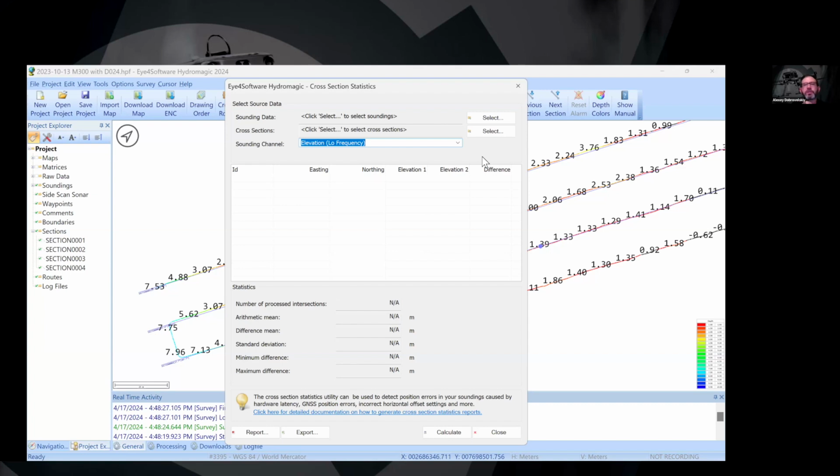And actually, if we do bathymetric surveys in some rivers and lakes, the elevation of the water surface can be different at different times because of tides, because of actually the variable amount of water in a pond, for example. It is better to compare the data for elevation.